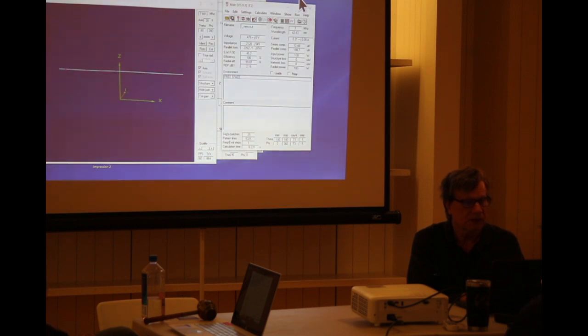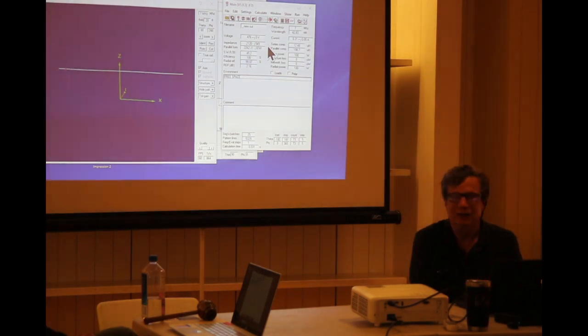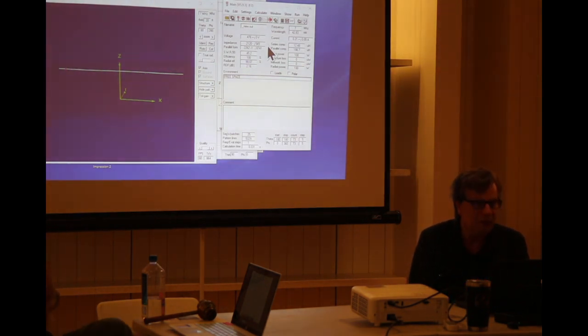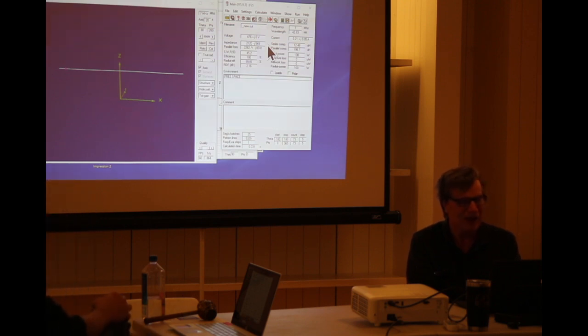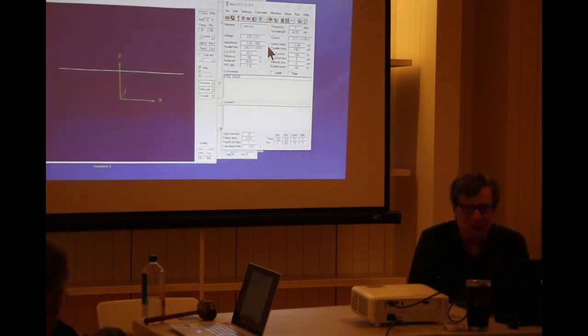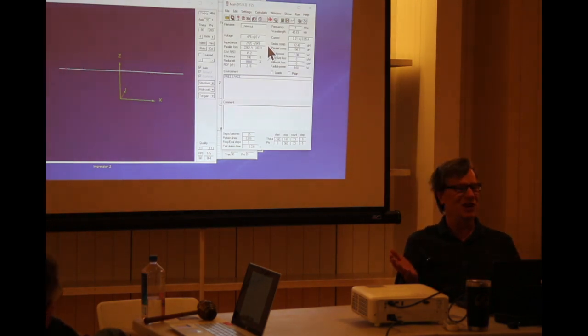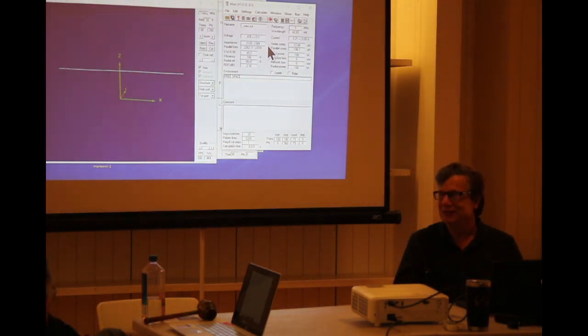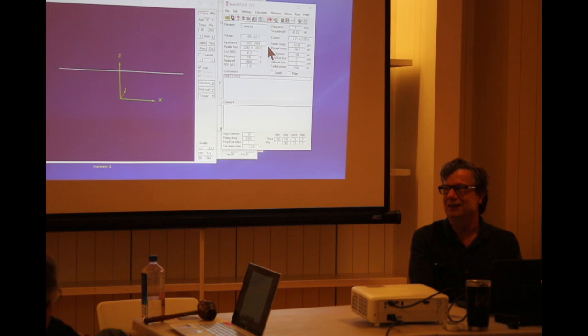The imaginary part, anyway. See how much that changed with just a really small change. The impedance changed some, but not as dramatically as the reactance. So just be aware of that. It doesn't mean you can't use it. Just be aware that, why does this antenna work as advertised? Well, we have to accommodate the reactance, and that can change quite dramatically.